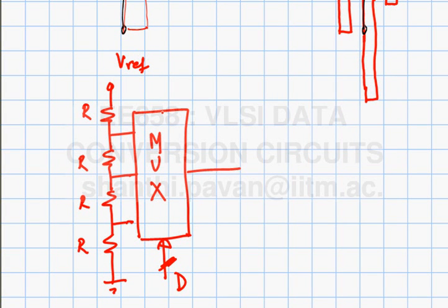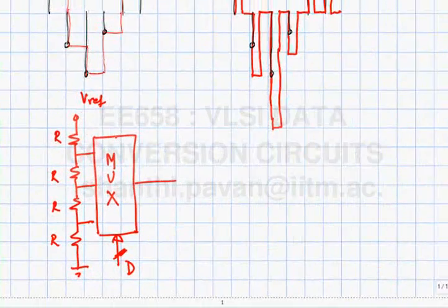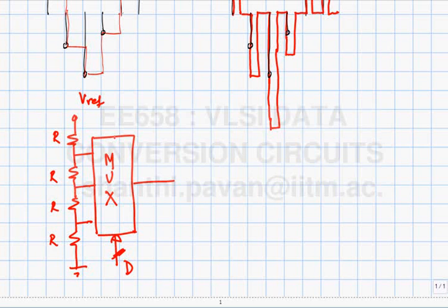That will give you the NRZ pulse shape without any hassle at all. In fact, to do a return to zero, you actually struggle, because after half the clock, you have to switch to zero. You understand? So generating the return to zero clock pulse is not complicated, but it's definitely not as straightforward as simply doing the NRZ.